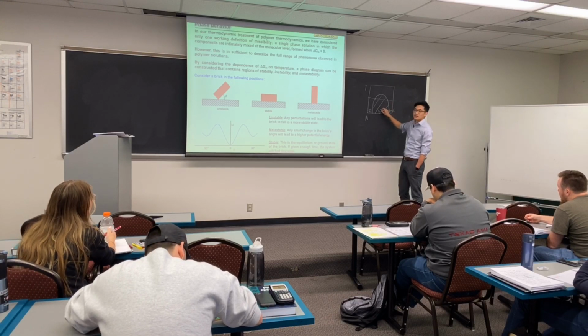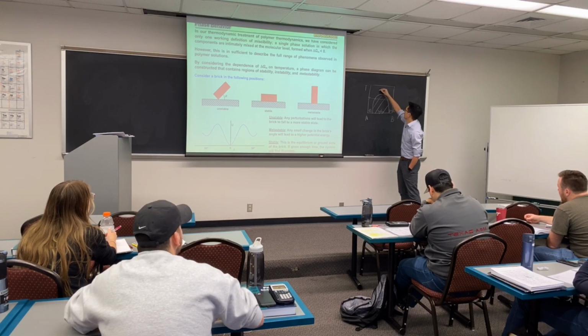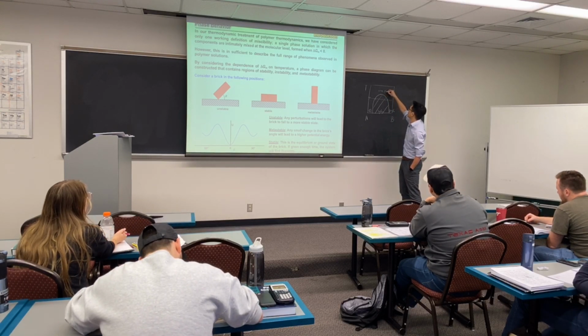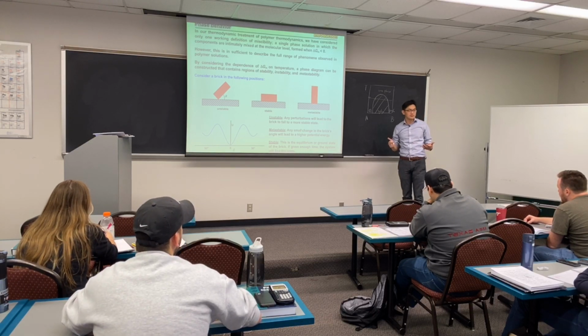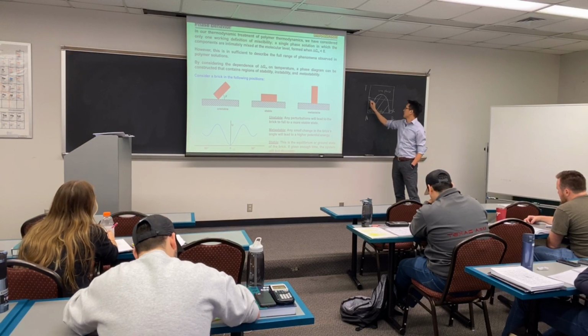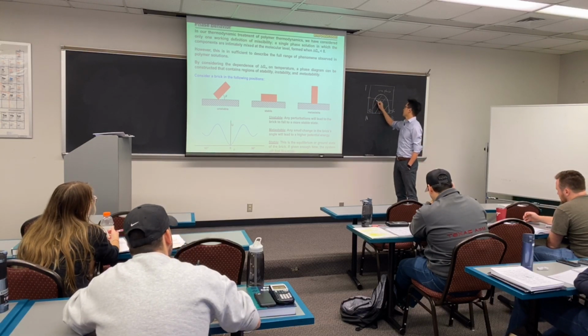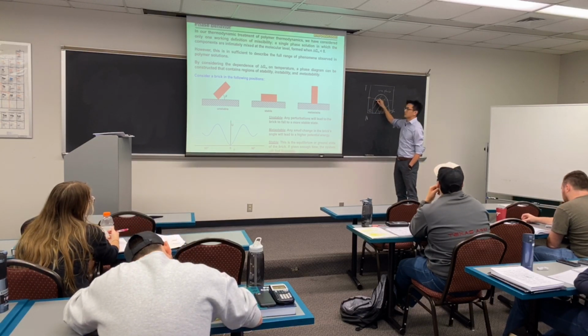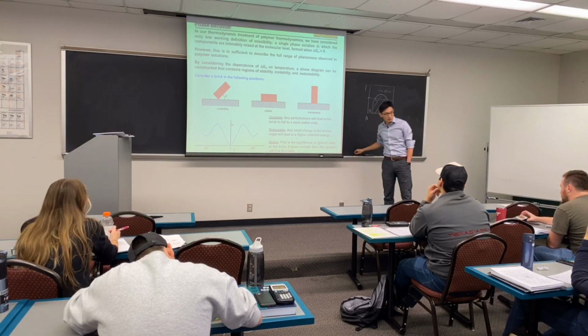Under this area, nothing will mix. And above that, it's called one phase, where everything will mix. So if you want to check this polystyrene, this polyethylene, and let's say this gives you the temperature scale, you check 75% at 50 degrees. If it's falling here, that means they will phase separate, okay? Very easy to use the phase diagram.